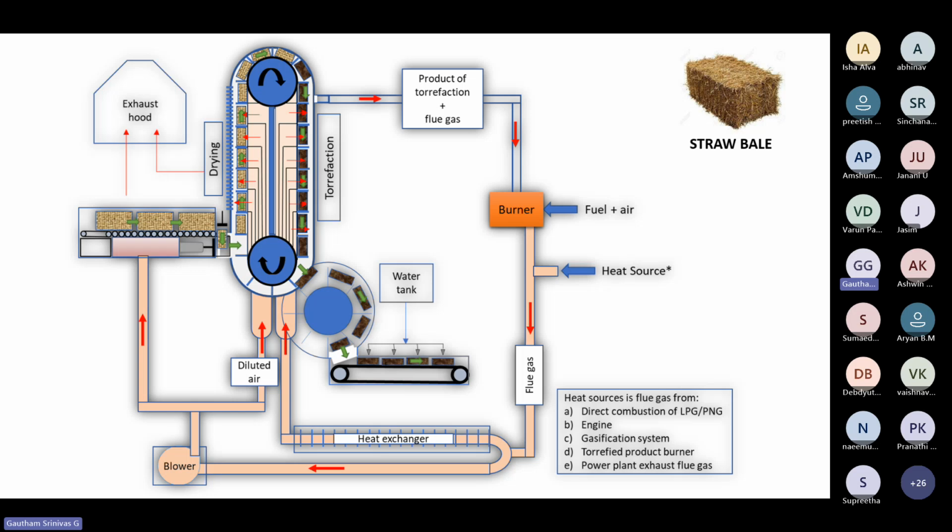In this case, about 400. In this case, about maybe 150, something like that. So why are we using direct mixing over here, but only a heat exchanger here? Why not use direct mixing of air in this case? Because if we mix direct air in the heat exchanger pipe... I'm talking about instead of heat exchanger, if we directly mix the air with the flue gas, what will